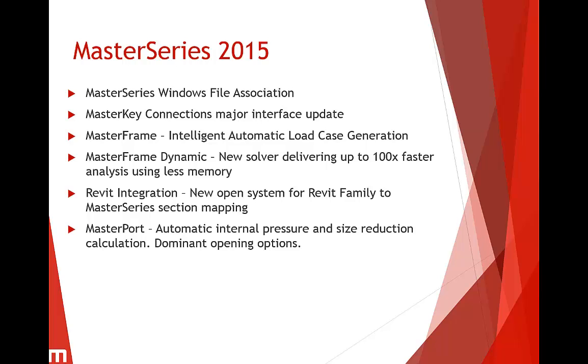MasterPort as well, we're going to be having a little look at. It's got some new options for automated internal pressure calculations, which takes account of size reduction calculations. Also automatic size reduction calculations for the external pressure coefficients. And we've got some nice options for dominant openings there as well, which all serve to automatically calculate those internal and external pressures.